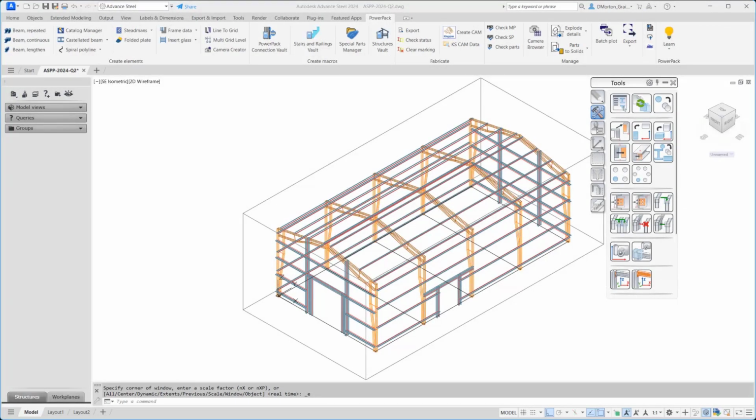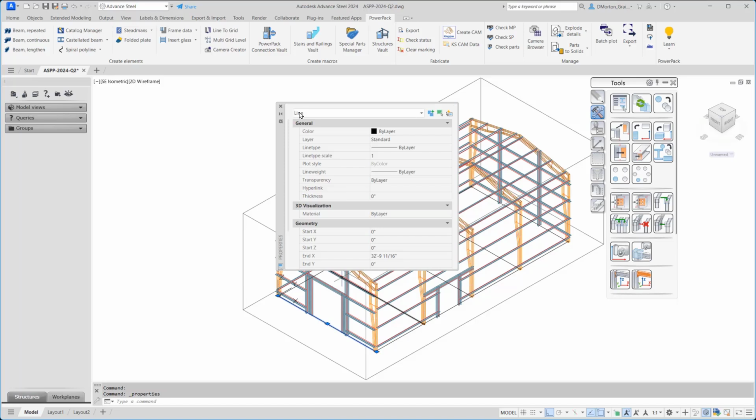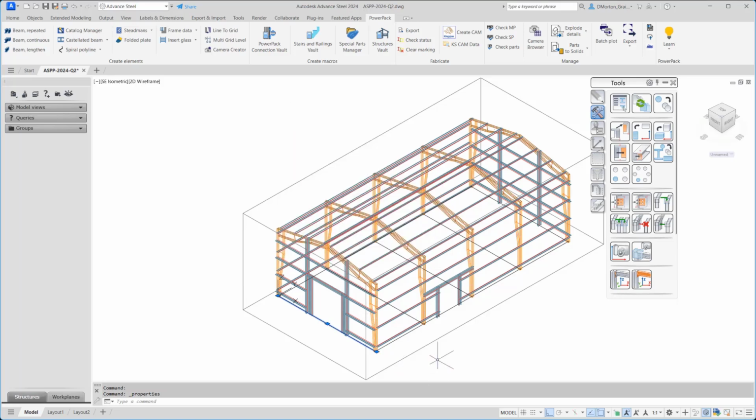Next thing I'm going to do here very quickly is I'm just going to put some grid lines in. I went ahead and just drew some regular lines. If you look at these lines here, they are just AutoCAD lines, that's all. And I put them where I want the grid lines to go. So I put one and I just copied it over a few times, and I put one over there and I copied it to here.